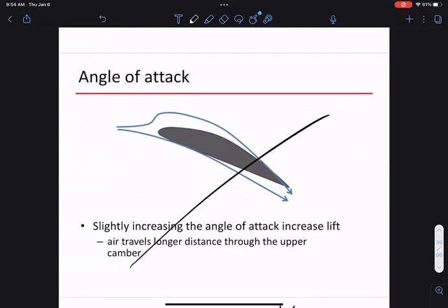So again, if you repeat the Bernoulli's principle, we try very hard to explain why the angle of attack matters and how the changing speed and changing length work. All this is in some sense bogus theory. So we're now going to explain things through the different distance air molecules travel. What we're going to say is, as the angle of attack changes, the way airflow changes, more air may get bent downwards, so you have more lift.